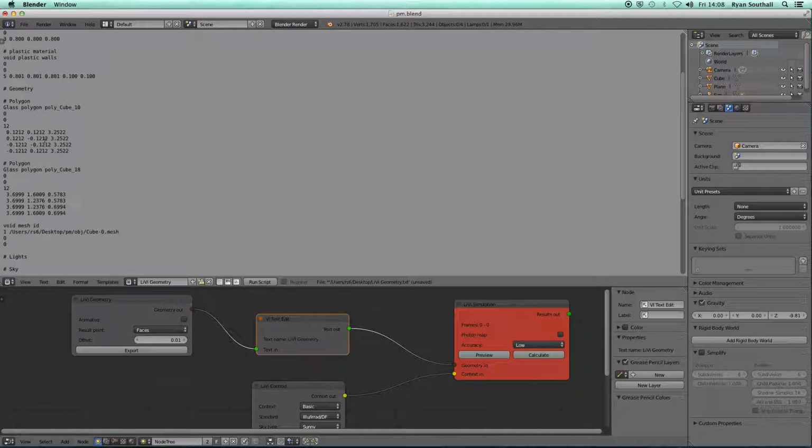There's two types of geometry in here. There's simple polygon geometry and there is Radiance mesh geometry. These have been created because these glass surfaces have got the photon port turned on from my previous photon mapping tutorial. And if a surface of a model has the mirror material associated with it, or photon port is turned on, and a couple of other situations I can't quite remember, then the vSuite will fall back to Radiance's very simple polygon export routine.